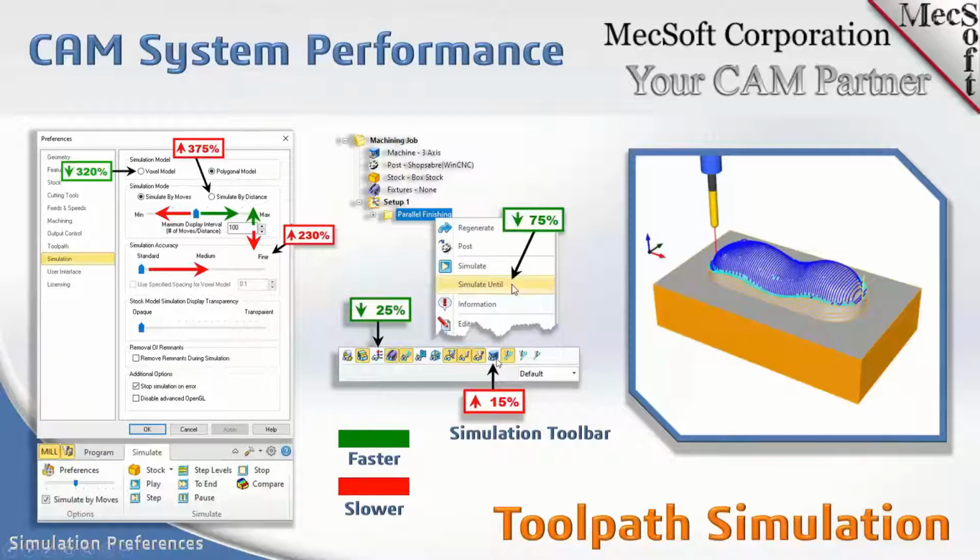Also over here, if you're in a pro or premium configuration and you're going to simulate your machine tool, that's where you have your machine tool on the screen and you're actually seeing the axes of the machine tool simulate along with the part, just be aware that's going to tax your system another 15%, so it's going to slow it down.